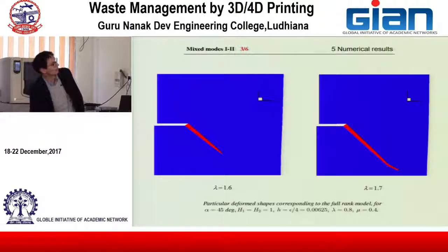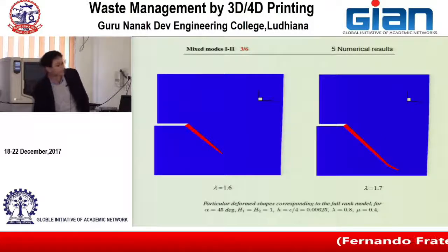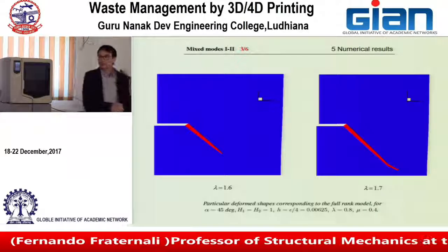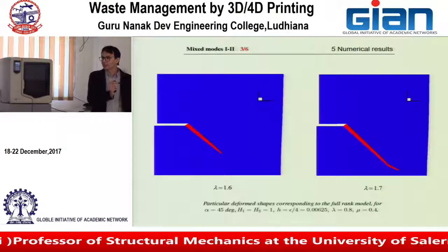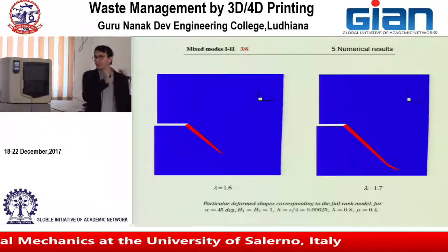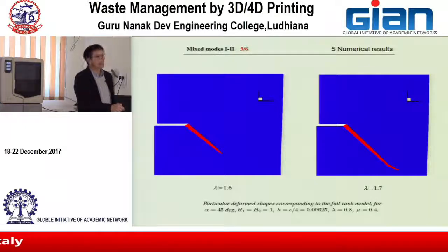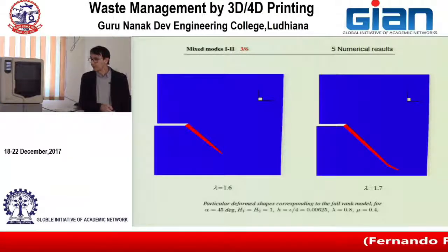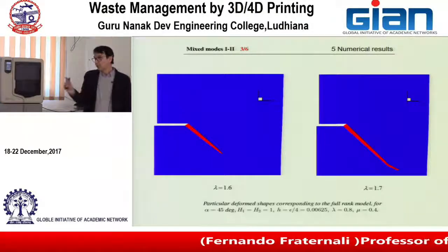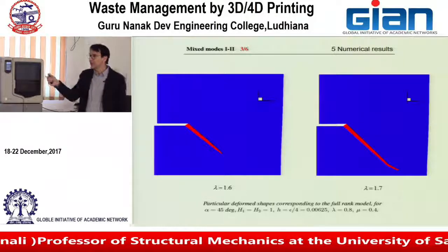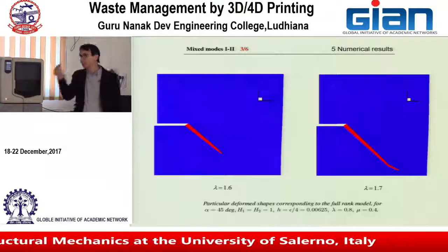What is epsilon neighborhood? You want to kill this element. Let's remember, you try to kill this element. What do you do? You set all the elastic moduli of that element to go to 0, and you obtain a different energy. And you compute the delta energy, the difference in the energy without killing the element and then killing the element.